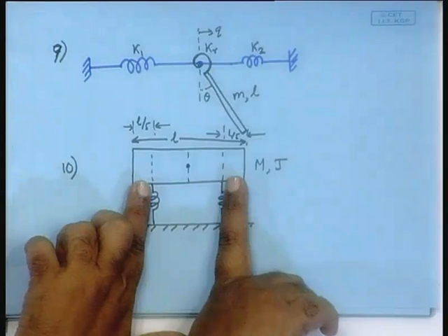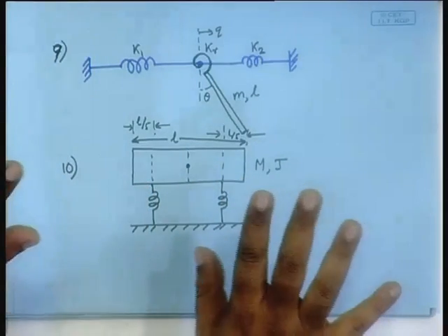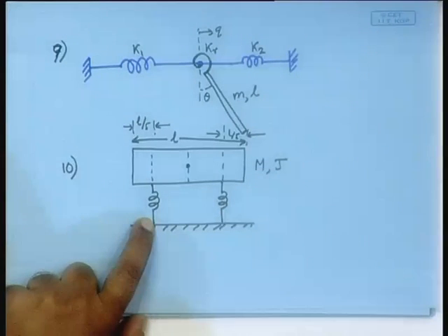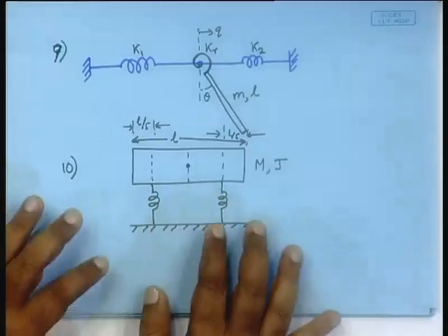Okay. So, in order to define the positional status of this system uniquely, how many variables do you need? 2, one representing this position and one representing that, and the elongation of the springs will have to be measured from both. It is not just this. If there is a tilt here, this particular spring is compressed and this particular spring is elongated. That will have to be taken into account in order to measure the potential energy in the springs. So, the problem is just a bar resting on springs, and if you press one, it will go on oscillating like this, and that is what we are trying to find out later, but the first job is to obtain the differential equations.